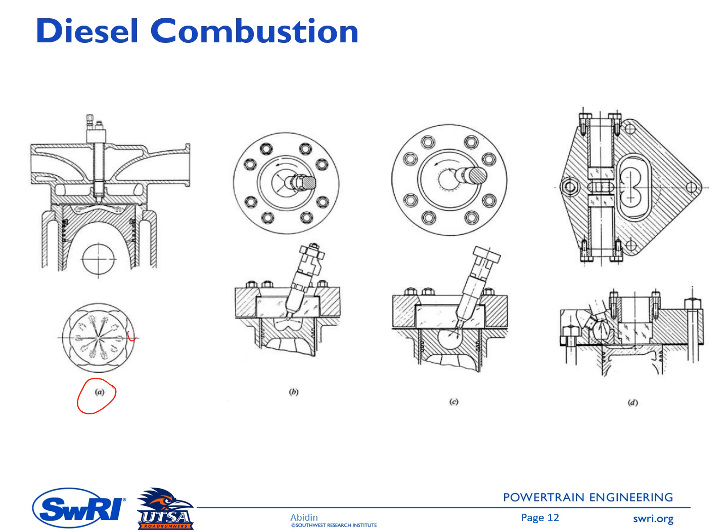However, it applies air swirl that enhances the fuel-air mixing process, and the swirl direction is counterclockwise. And then system C here has a different shape of the piston bowl. And then D is the one with the pre-chamber. The pre-chamber is on the left side here, and there is a nozzle connecting the pre-chamber to the main chamber here.